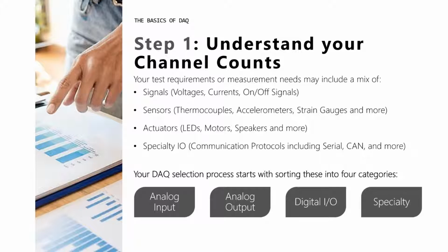Let's go to step one, understanding your channel counts. Your test requirements or measurements may include a mix of signals. Signals could be current, voltage, on and off signals. It can also be mixed with sensors like thermocouples, accelerometers, strain gauges, and more. It could also include actuators like LEDs, motors, speakers, and many more. It may also include specialty I/O, such as communication protocols like serial, CAN, and Modbus.